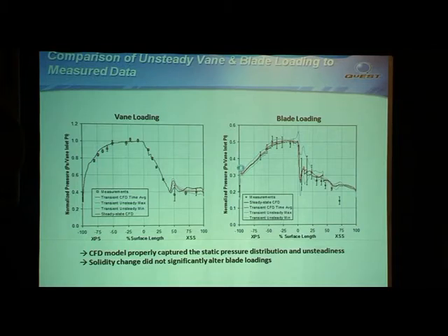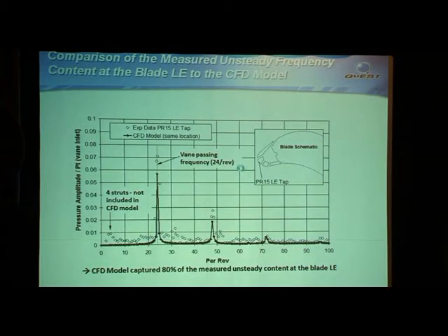Similarly on the blade, we had good agreement with the mean data, which is the symbols here. And the other thing that we were happy with in terms of the agreement was, if you note that the unsteadiness in the measurements here on the blade suction side was matched pretty well by the range of unsteadiness in the analysis. So we thought we were on the right track in terms of capturing the unsteady loadings on the airfoils.